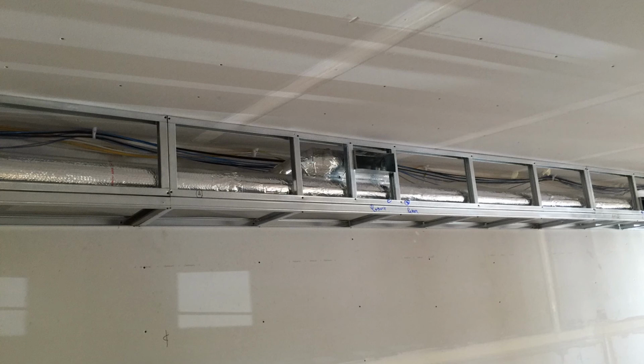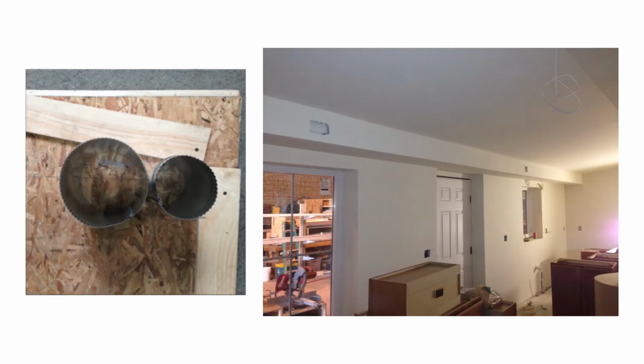Here's a photo of the duct trunk in a soffit with an example of a simple takeoff and a register. Notice that the ducts are sealed and insulated, and the duct trunk was built after the drywall was hung and taped. This we do in order to minimize heat loss to outdoors. Remember, we're trying to keep all the ducts within the conditioned space. So if we want them to be 100% in the thermal enclosure, that means that the drywall air barrier has to be intact on the backside of the soffits, so we don't have a leaky air pathway to outdoors in our duct soffit. Here's a couple more photos of the trunk.